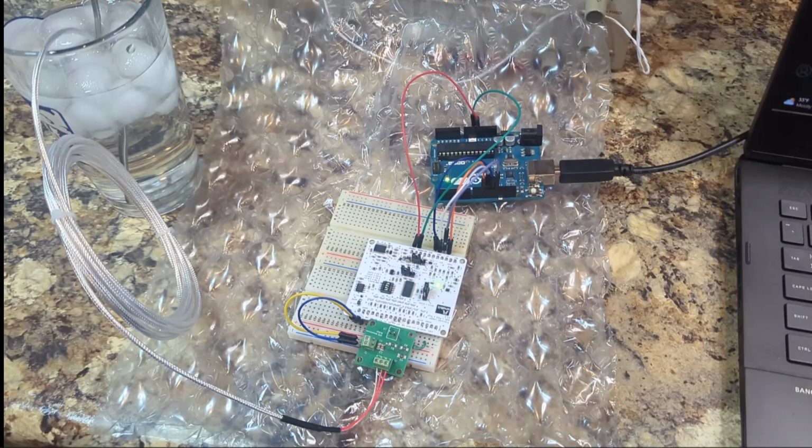Here we have our same circuit, except now I replaced the Wheatstone Bridge with the same design as the Wheatstone Bridge you just saw, but now I have 1,000 ohm precision resistors instead of 100 ohm. And then I have a 3-wire RTD sensor that's a PT1000. So we went up to a higher resistance.